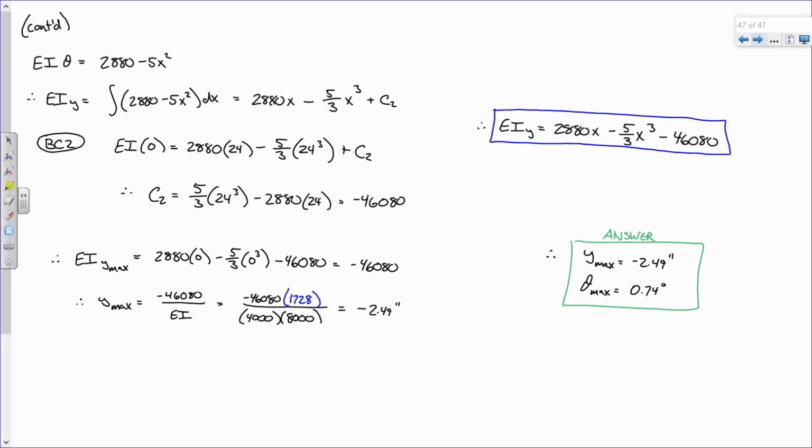Make it deeper. And so analytically, what does that do to these numbers? So it bumps up your I value. So one potential option is to increase your moment of inertia. And you're saying to do that by increasing the depth. And that is correct. There's a couple other ways to do it. You could increase the width, but it's not as effective as increasing the depth. So increasing the depth is a way to improve this deflection, make it smaller, by bumping up your moment of inertia. Somebody else, what's another thing that we could do to this beam?